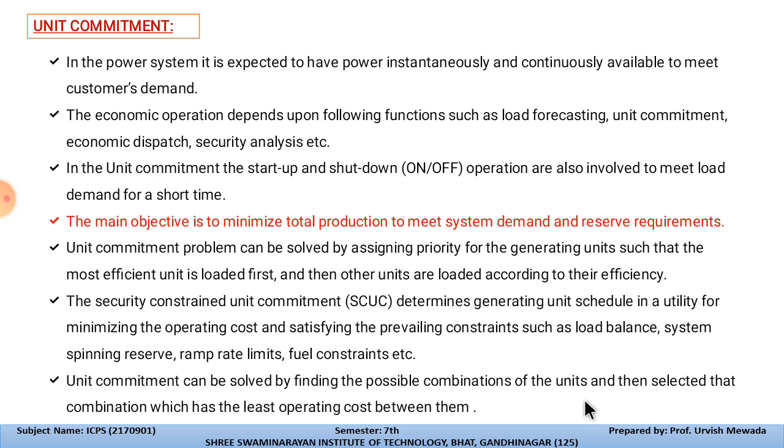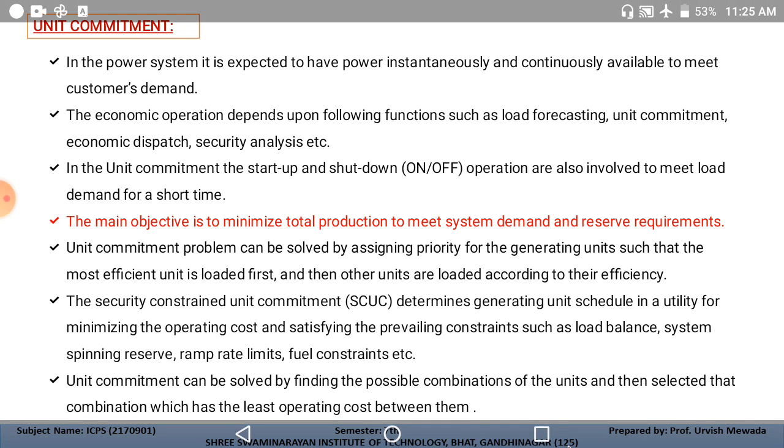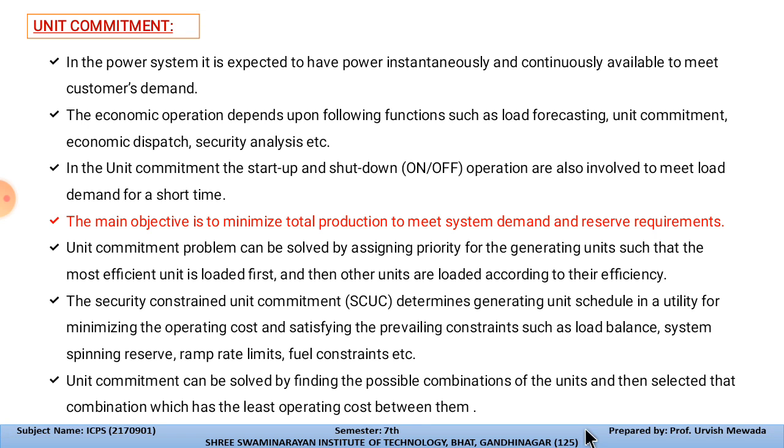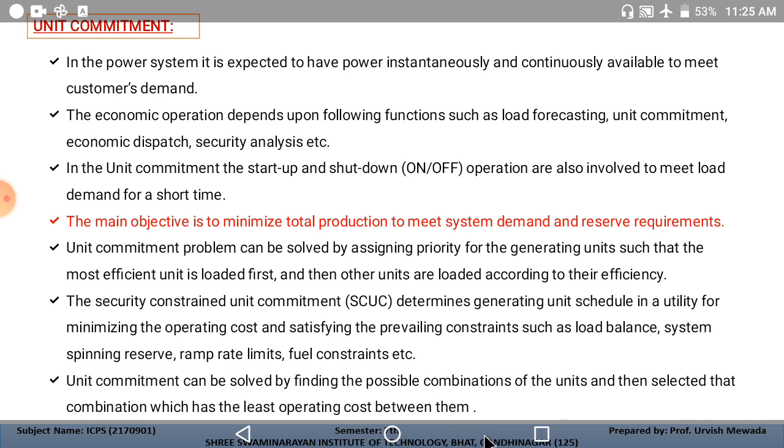It is necessary because switching the generating units on and off will save the generation cost of the power system. If the demand is less and the plant is generating the same power, and it is not taking part in load shedding in the power system, then that power will go to waste. So we need to switch our units on and off according to the consumer demand.